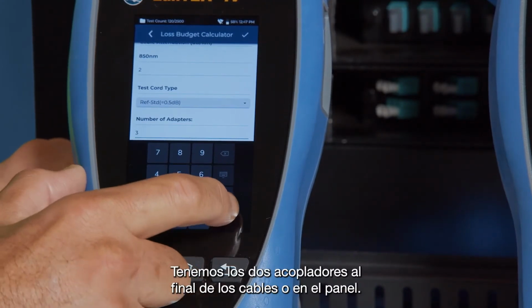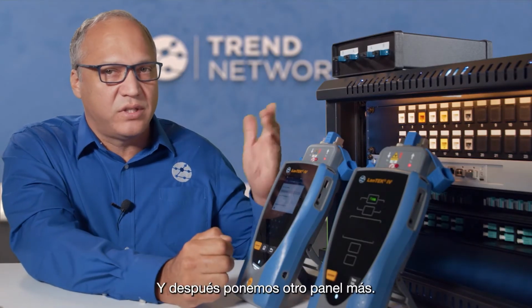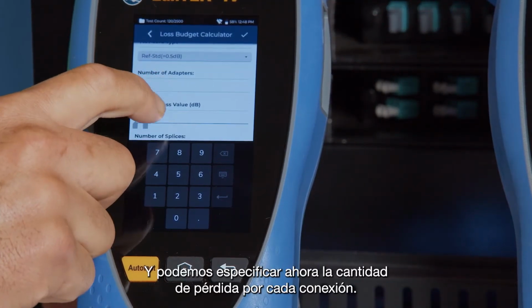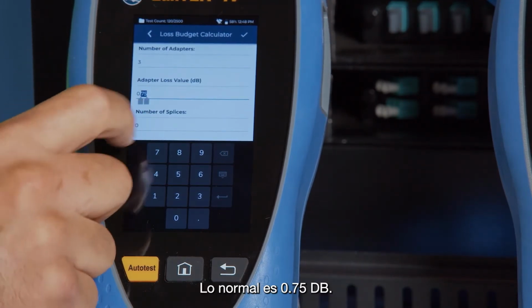So we have the 2 couplers at the end of our test cords or at the panel, and then we'll say there's 1 more panel. So there are 3 connectors in total. And now we can specify the amount of loss for each connection. The standard is 0.75 dB.